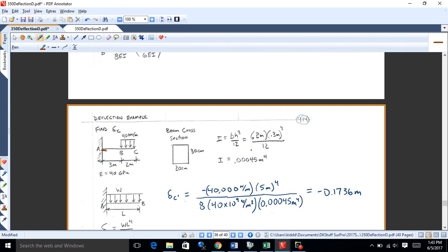This is going to make the beam bend down, but it's also going to curve it throughout the length. If that were just a load at the centroid, it wouldn't deflect the same way. It would curve probably a little bit more dramatically to here, and then it would extend out straight from there. So the shape of those beams are just going to be different. It's not quite as straightforward as when you're doing reactions and statics, because we're doing more with it. The shapes of these curves are going to be very different. So that's the quickest answer I can give you on that. Okay.